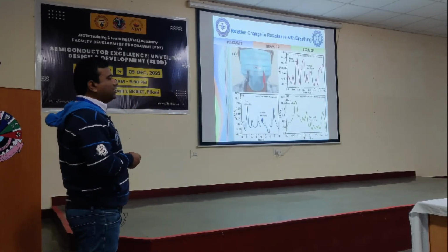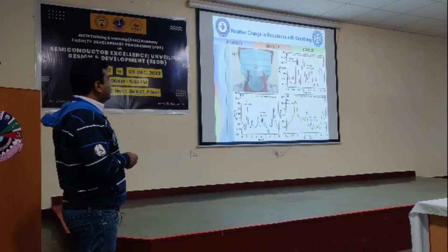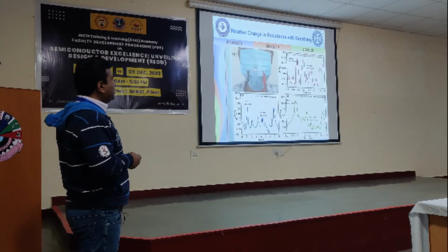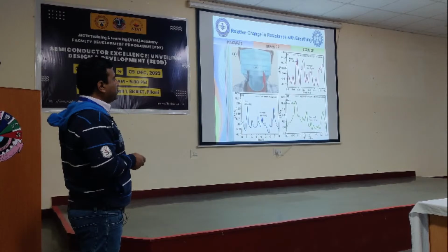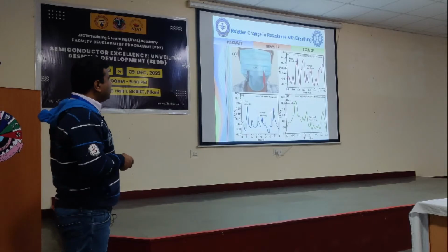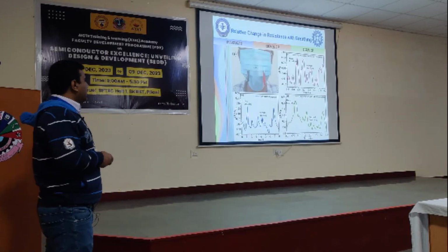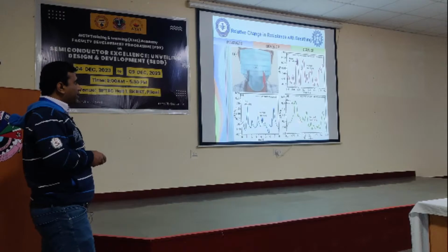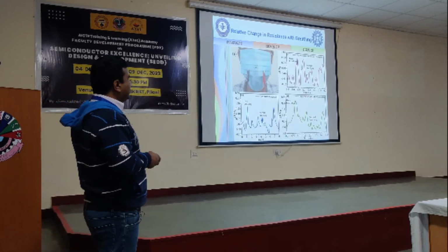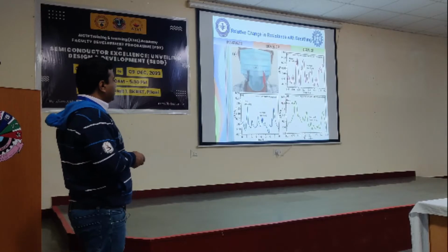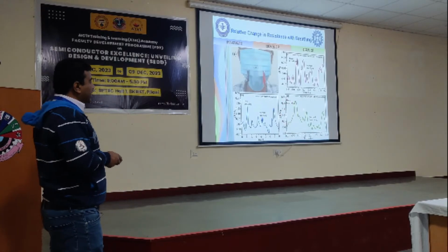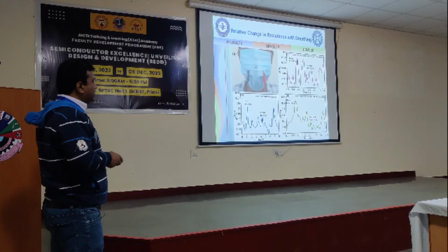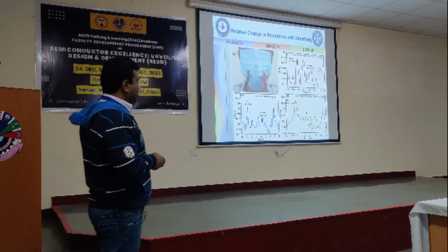Now whenever you mount the devices for breathing analysis, you see, this is the device when you are mounting it onto your mouth. Whenever deep breathing is taking place, the change in resistivity is high, but whenever normal breathing takes place, the change in resistivity is quite low. That also ensures that each device is very sensitive. In the GNP PDMS case, you see a very prominent peak is there in the case of silver nanoparticle GNP. In that case the change in resistivity also gets higher, and whenever normal breathing is taking place, the device is also sensing.